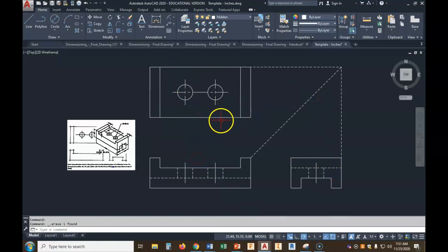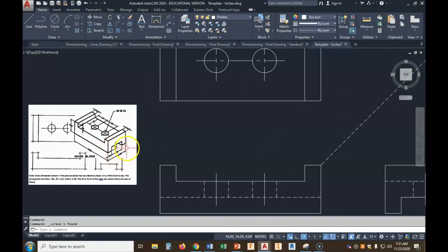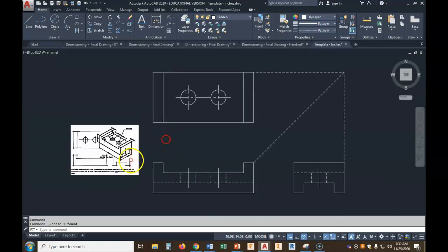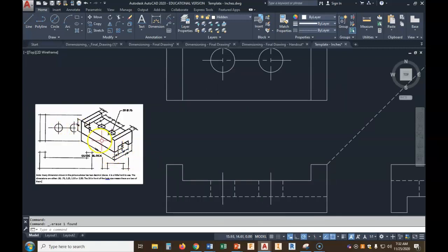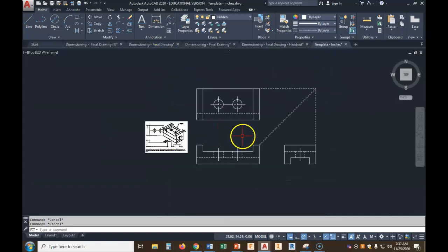Well, like I said, if your mind's working the way it should, you got your math in your mind. So it's a 1/2 inch from the front back to that slot. So line from the front, hover, come back, 0.5, and it goes all the way across. Don't lose sight. Don't start here and go to here. The slot goes from the far right edge to the far left edge. Okay? Get it in the right place. Now we need another one here. Very same distance. Mirror will work.